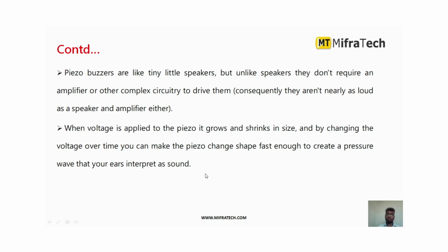Whenever we apply voltage, the material in the piezo buzzer grows and shrinks. According to the change in the shape of the buzzer, a wave is produced, which we can hear as sound. So this is how a piezo buzzer works.